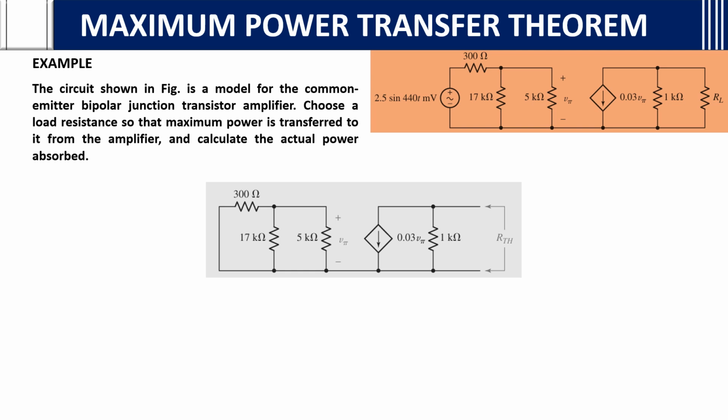If you see the diagram, you need to first get RL. Here we are using Thevenin's theorem. For using Thevenin's theorem, what we do is open circuit the terminals first. Then here we are first finding RTH. For finding RTH, we remove the voltage sources, so I short circuit the voltage source. Then we have written the other circuit as it is.